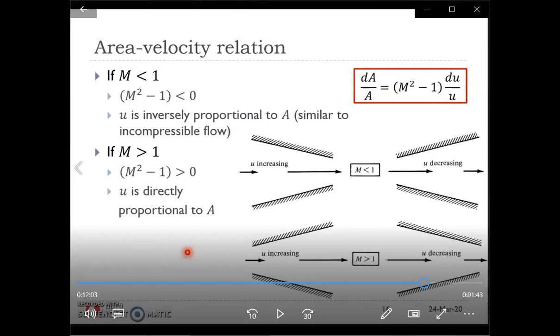basically the incoming flow is supersonic. Again, considering our faraway boundary like a straight streamline, far away from the body. At the corner, when the flow sees a ramp, it suddenly sees an increase in area. And the incoming flow is supersonic. Again, now due to this area velocity relation that we are seeing right now, that must cause an increase also in velocity, also in Mach number.